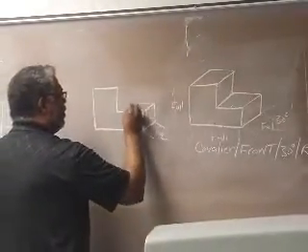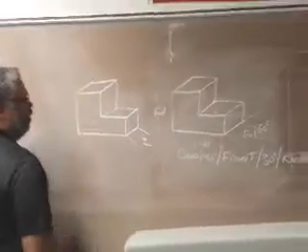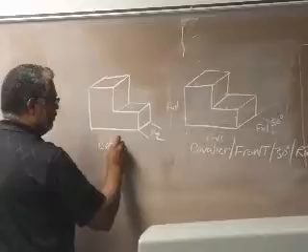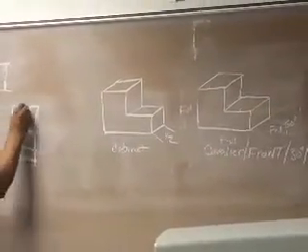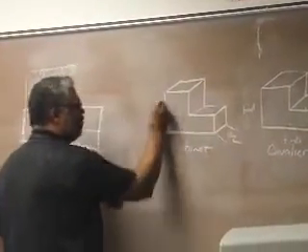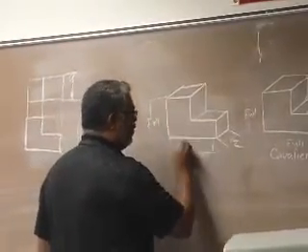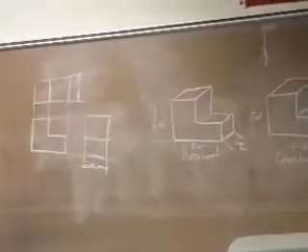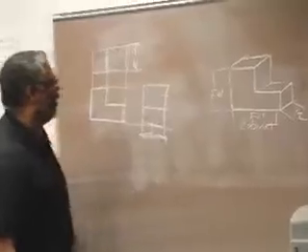That would give us a cabinet. So this would be a cabinet oblique. Whatever our depth is, we're halving that depth. This will be the full distance here, and of course full there, but we halve the depth. So we're basically just scaling on the depth.